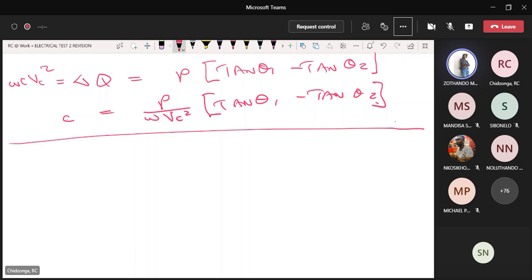No, that is wrong. Okay. Remember, what we are getting is kilovars reactive. This 7.3 is kilovars reactive. So you cannot just equate it to the capacitance. It is capacitive reactive power. So capacitive reactive power, you calculate it by the voltage across the capacitor squared over the capacitive impedance.